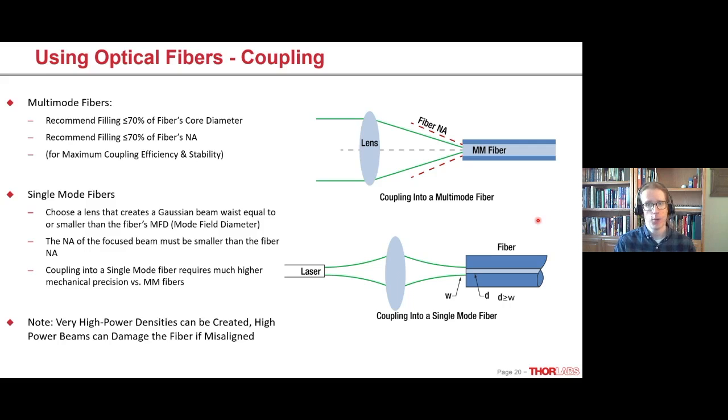And it's just connected to one end of a long fiber spool. But with a very sensitive detector, it's going to look for that pulse to come back, to be reflected somewhere in the fiber and come back to the instrument, which is connected to the fiber spool. And not only does it look for that pulse, it looks for intensity, and it times how long it takes for that pulse to get back.